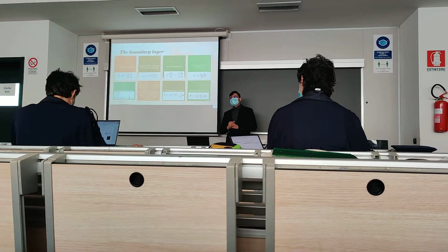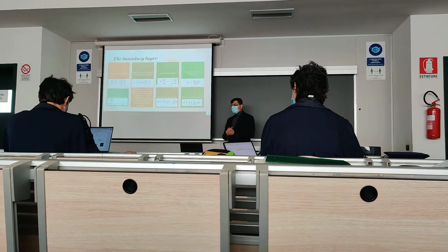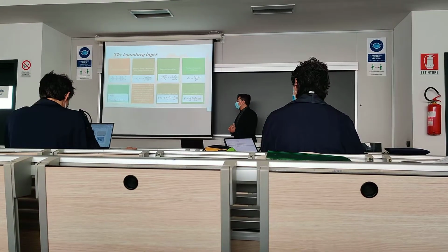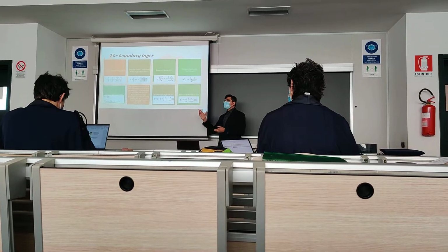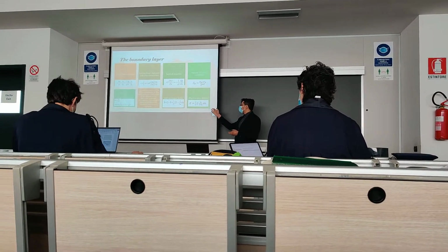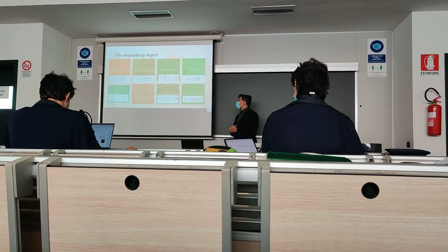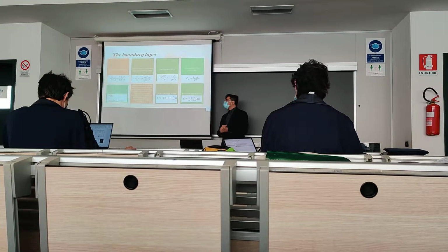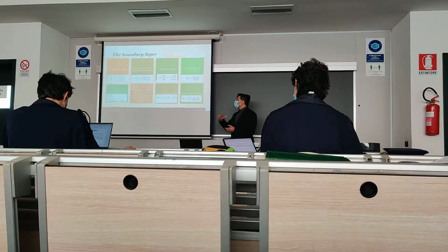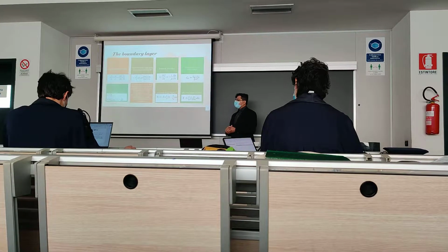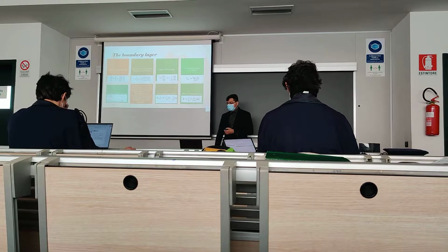It is 1 minus the effective area fraction. This effective area fraction is 1 by A times the integral of u by um dA, where u is the local velocity, um is the maximum velocity, and A is the overall area. So we have to increase this effective area fraction and reduce this inlet blockage factor.